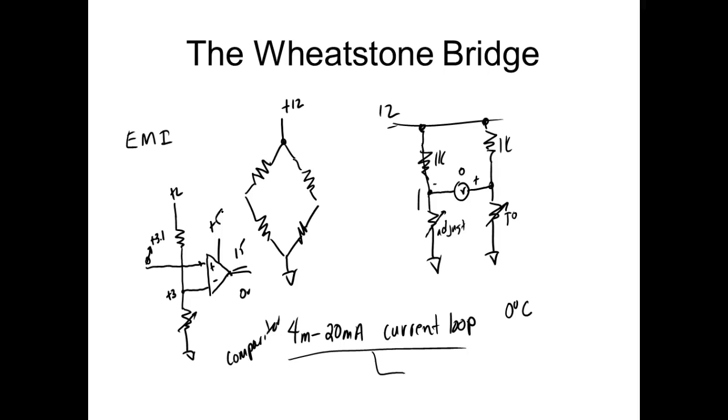But that's what you're doing. All you're doing is setting the reference voltage on a comparator, and then if it exceeds it, it does what? It just flips. So we use a lot of these. I could take the output of this, and this could be my comparator, and input that. So these are several circuits. Wheatstone bridges give us the ability to establish a zero. It gives us the ability to have a negative or positive: if you go below 0, the voltage will go negative. If it goes above 0, then the voltage will go positive.